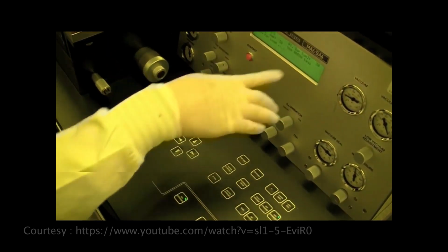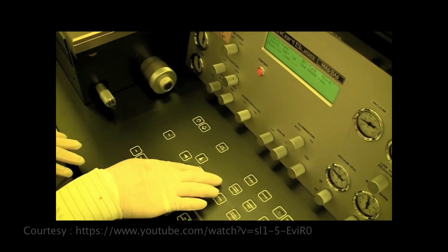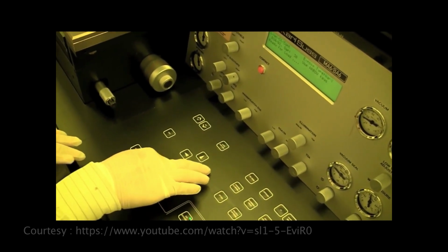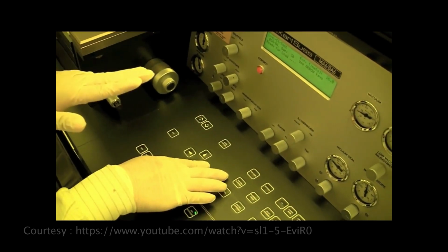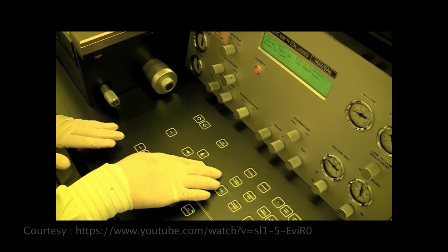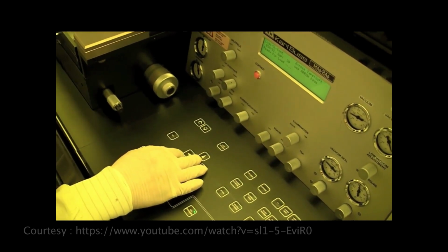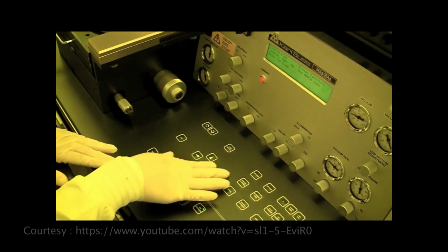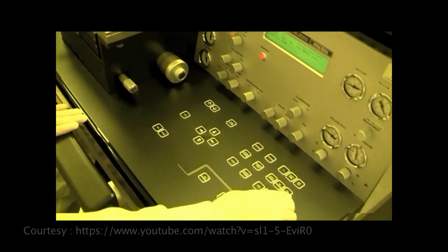Let's change the alignment gap. Let's make that 40. And then let's change the type of contact, we'll make it soft contact. And now the parameters have changed. There's different types of exposure types, from soft, vacuum, hard. You can look at the supplemental to get more information. But right now we'll set it as soft. So once your parameters are set, you can hit edit parameter.